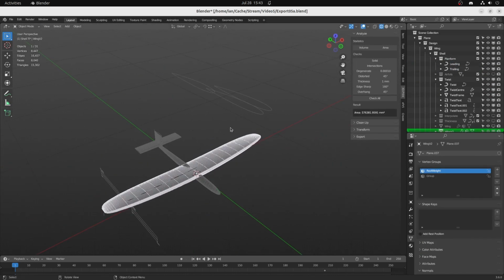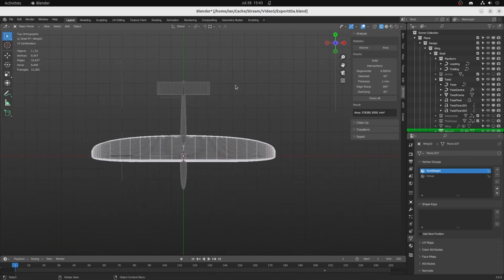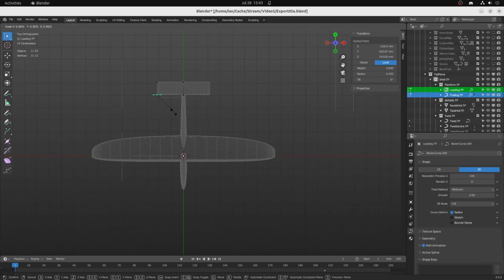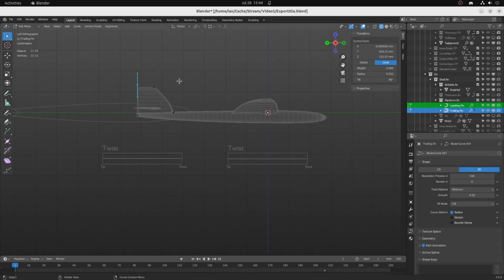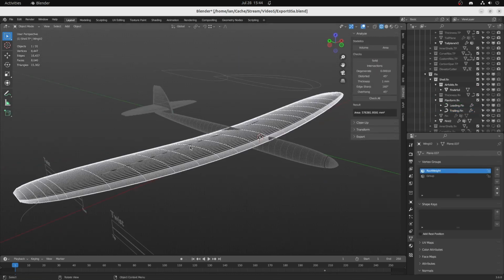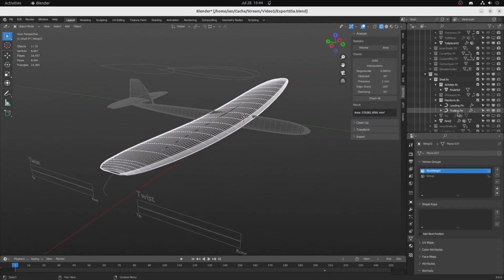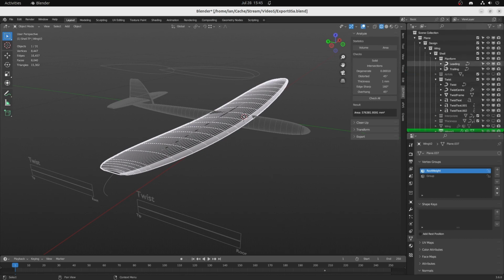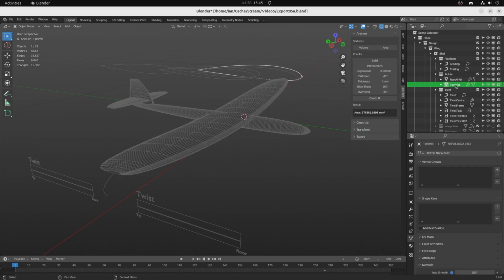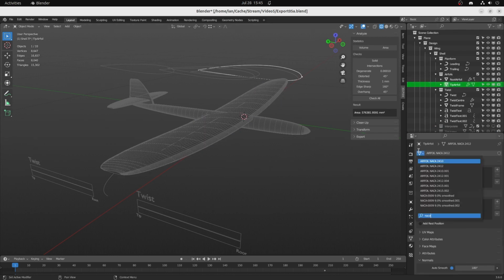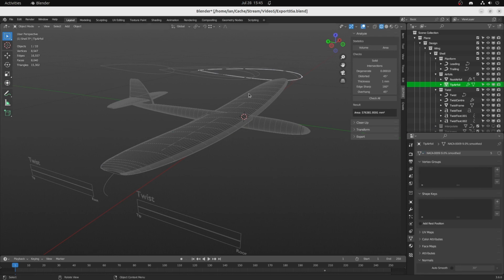Okay, that's pretty close, and I'll also just streamline a little the tailplane and the fin. I'll also choose a different airfoil for the tip, and we'll make it a non-lifting airfoil that only affects the very tip of the wing. We'll go back to the wing, look at the tip airfoil, which is currently an NACA 2412. We can look for a symmetrical wing section. Perhaps we'll go for a 9% NACA 009.